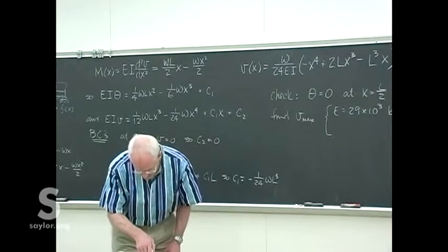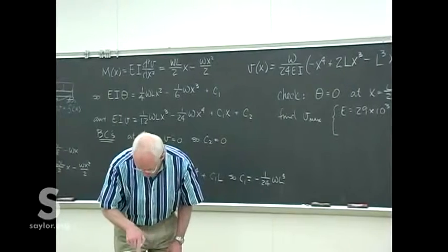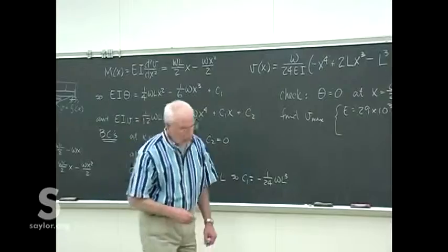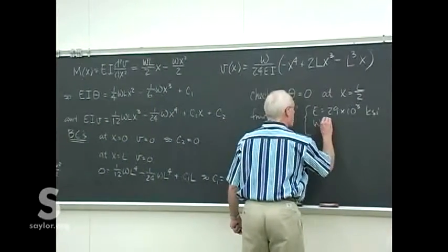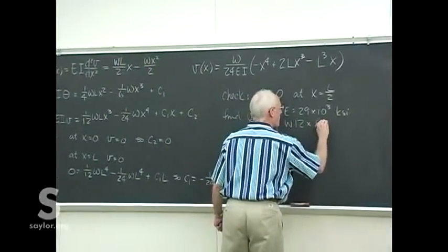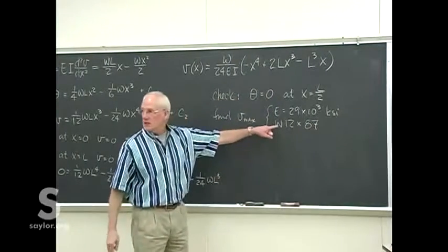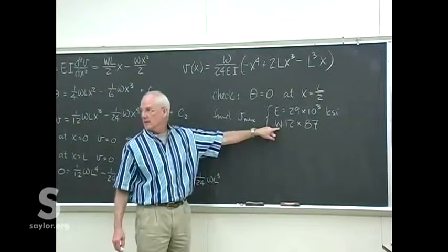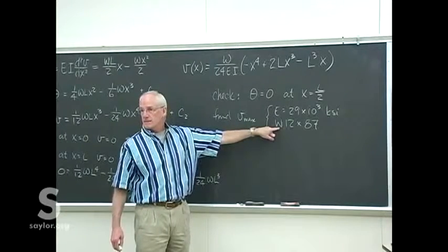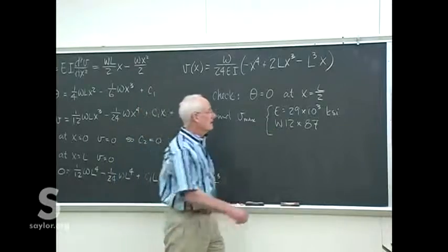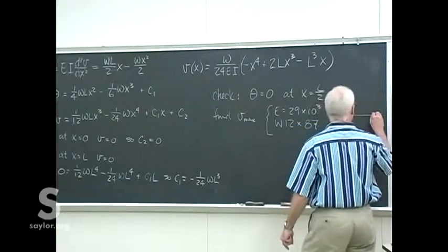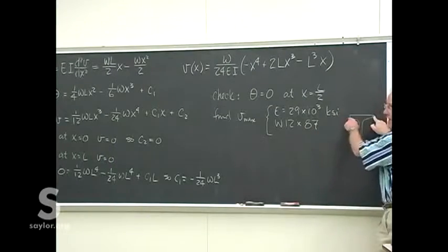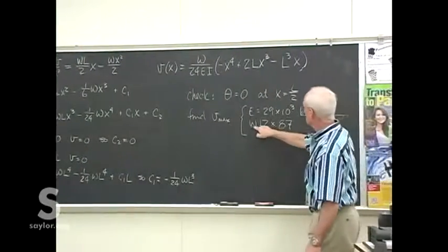So pick a fairly heavy beam here. Let's pick a kind of a little beam, but a heavy beam. So we'll say a W12x87. Remember what these two numbers mean? What's the 12 mean? Well, actually, first, what's the W mean? Remember offhand? W means it's a wide flange beam. So it's an I-beam with what's considered a wide flange on it. So that's the W. What's the 12?